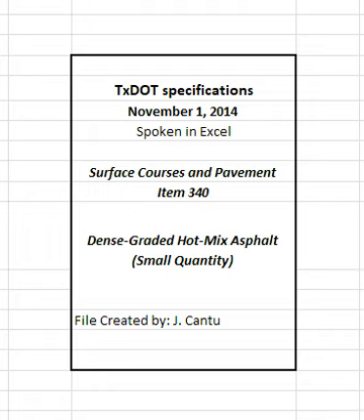4.8.3.2 Hamburg Wheel Test. The engineer may perform a Hamburg wheel test at any time during production, including when the boil test indicates a change in quality from the materials submitted for JMF1. In addition to testing production samples, the engineer may obtain cores and perform Hamburg wheel tests on any areas of the roadway where rutting is observed. Suspend production until further Hamburg wheel tests meet the specified values when the production or core samples fail the Hamburg wheel test criteria in Table 10.